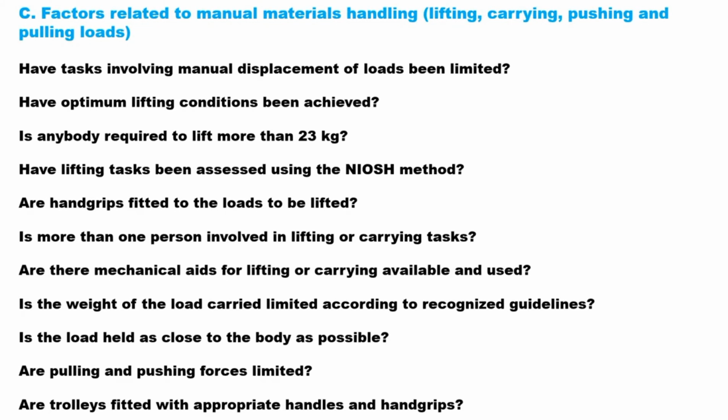C. Factors related to manual materials handling, lifting, carrying, pushing and pulling loads. Have tasks involving manual displacement of loads been limited? Have optimum lifting conditions been achieved? Is anybody required to lift more than 23 kilograms? Have lifting tasks been assessed using the NIOSH method?